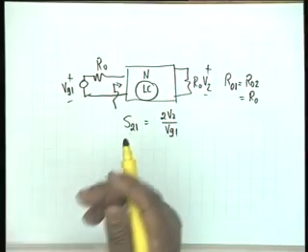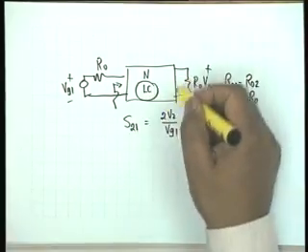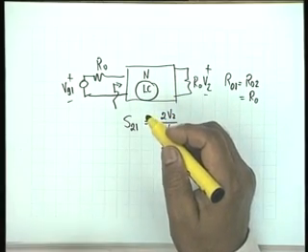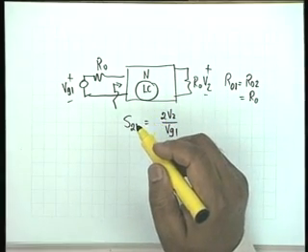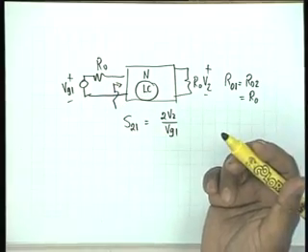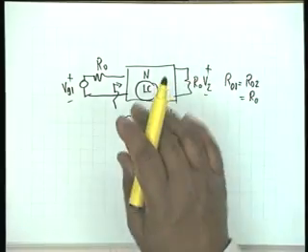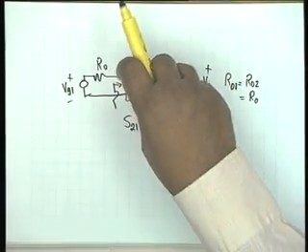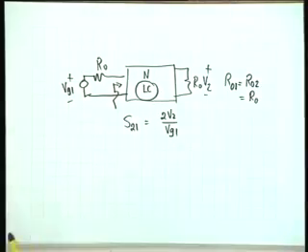One is that if it is a single frequency application, then all we want is that the network, the insertion network, the network that is inserted between the source and the load should be such that maximum possible power is transferred at port 1, which means that our aim is to make N such that the input impedance is approximately equal to R0. Agreed? Under that condition, the source gives the maximum available power. And then this network is to be lossless such that none of this power is absorbed by N, but is transferred to R0.